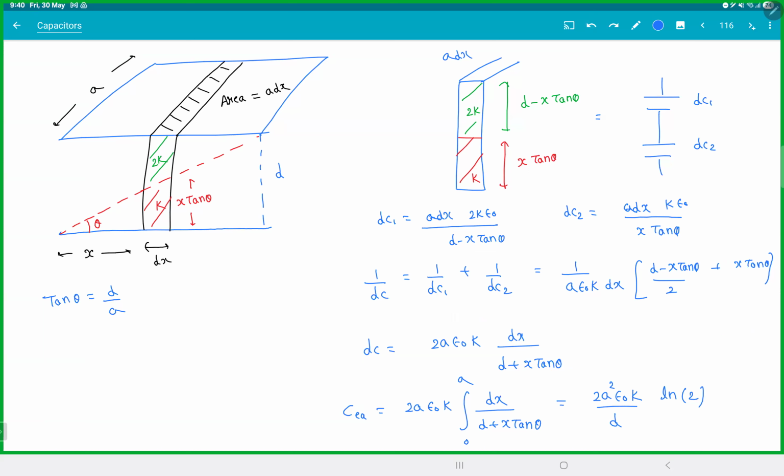So the main idea is this. You take a vertical element. Why can't you take a horizontal element? If I take a horizontal element, do you think within this element, is the potential same everywhere here? That's the problem. That entire face will have different potential everywhere on this surface. Don't know what to do with that. So when you take vertical, I know the same charge will flow, and then you can take the vertical strips to be rectangles to be in parallel.